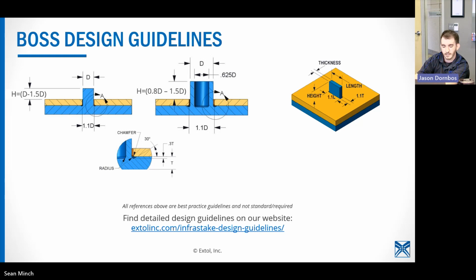Then if you look at, say, this through hole, that's pretty important. That will really drive your tensile strength. And there's a little bit of a range that we'll show later on, but how tightly can you design that through hole of the mating part to the boss OD? A couple other things to highlight here is there's a little bit of a range that we like to see for solid bosses. Also hollow bosses with the core pinned out here. And then we can also do tabs, so anything that is a little bit rectangular, if you will.